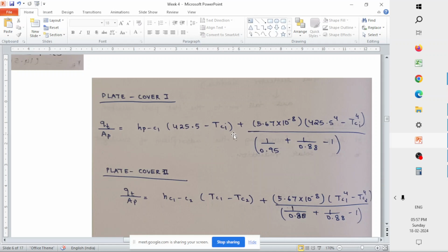So this course is particularly designed in such a way that you focus more on the geometric design as well as the thermal design of the flat plate collector. There are also other kinds of designing or modeling of the flat plate collector, like in terms of your material modeling. So the absorber plate that we use should be a selective surface, and it should be coated, it should be black in color.